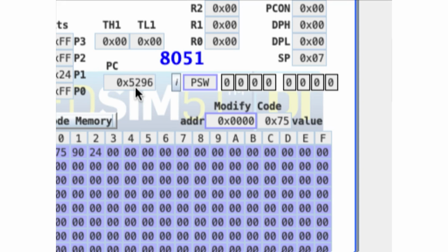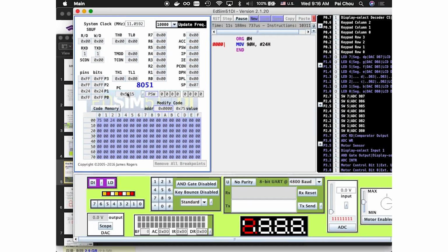16 bits. 2 to the power of 16 is 64K, right? 65536. So that means the program memory is 64K bytes, and that's a 16-bit address space. Okay, you should know this. If you don't, you probably shouldn't be taking this class. So anyway, what it's doing is going from the beginning of memory all the way to the end and then comes back again, right?